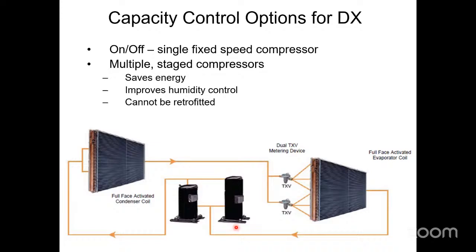So if you unequally size, I don't know if that's even a word, if you unequally size the 2 compressors, then you can get 3 stages out of 2 compressors. And that's, in fact, what's being done in this situation here. But once again, 3 stages is not enough for VFD.